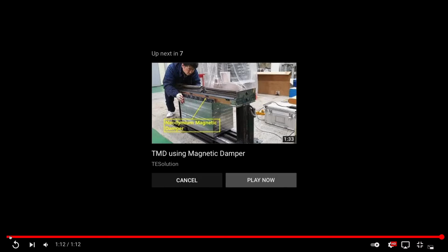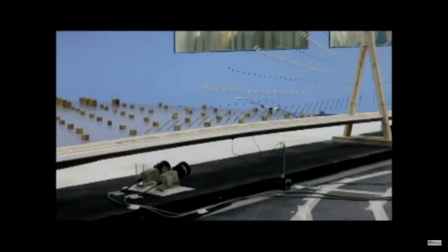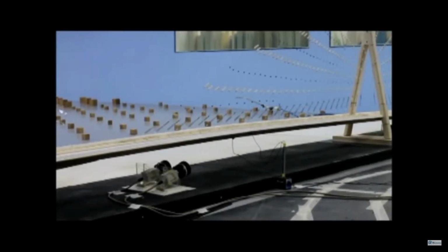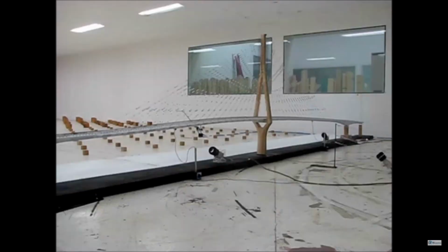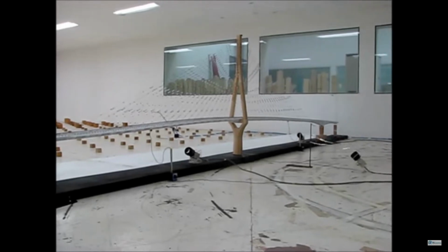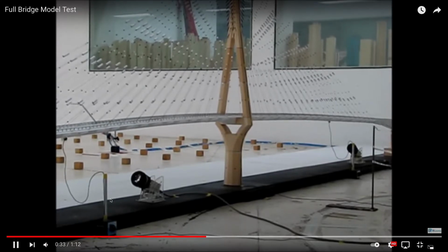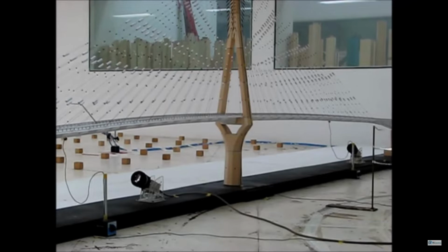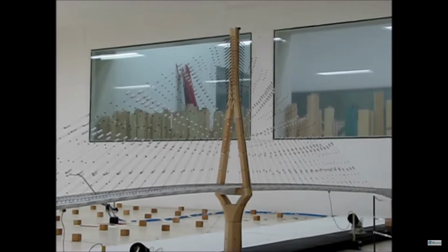The mechanism by which it works, I think we might have talked about it when we started off in the class, is that when wind gets shed on the other side of the girder, it'll alternately create a vortex off the top and then shed one off the bottom in sequence and keep on doing that, top, bottom, and that vortex gives a little jolt to the bridge, and it is in some kind of frequency that's related to the wind speed. So if the wind speed happens to be just the right frequency for that resonance, if the excitation from the wind, because of the geometry of the bridge, gives the right impulse that's identical to the resonant frequency of the bridge, then that's a problem.